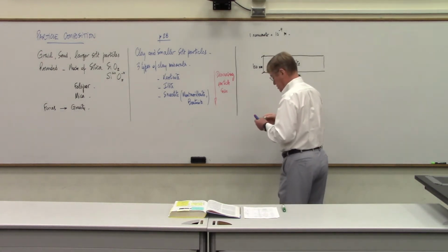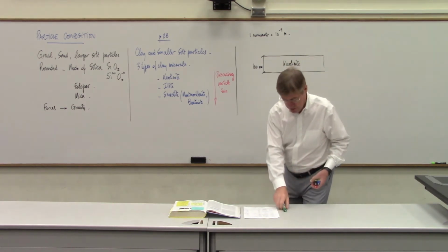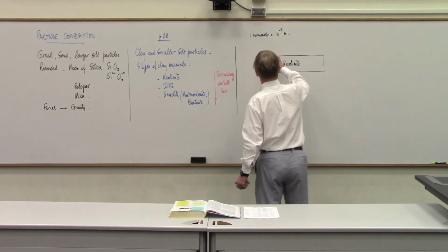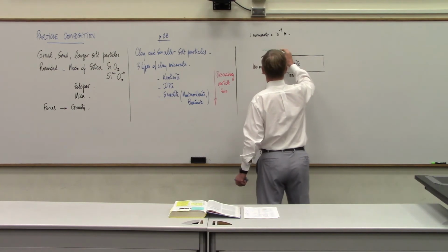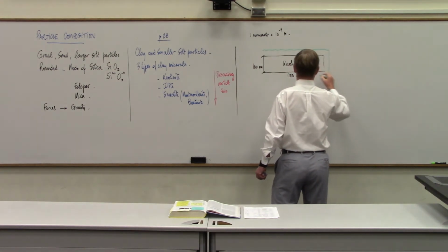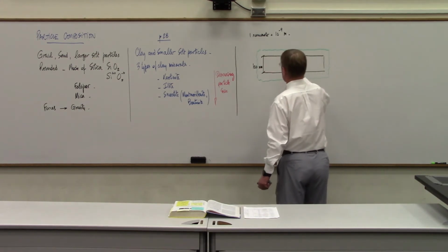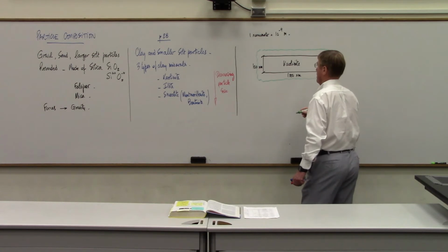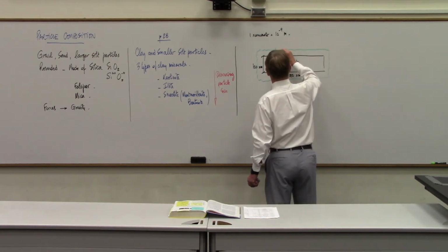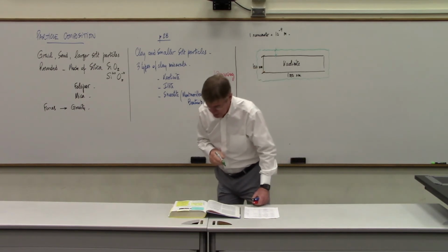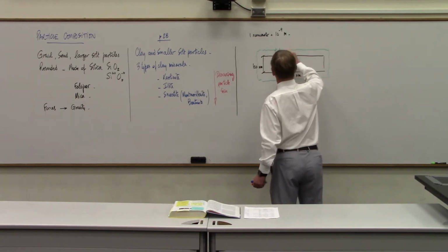It is coated, we'll come back to this, with a layer called a layer of adsorbed water. And so this adsorbed water layer coats the particle all the way around like this. And we'll see why the water is attracted to the minerals, to the Kaolinite mineral. And that thickness right here is of the order of 40 nanometers. So this is about 40 nanometers.